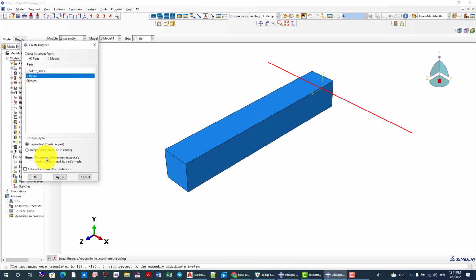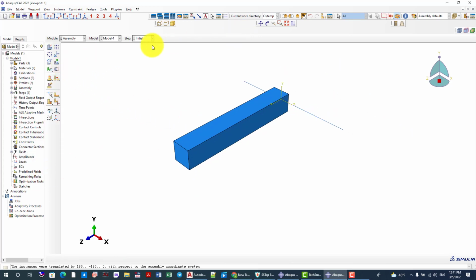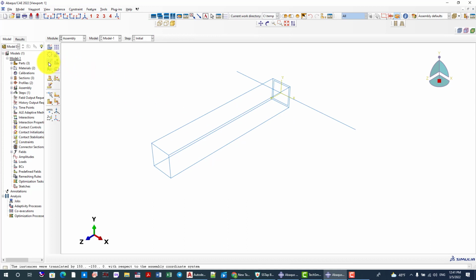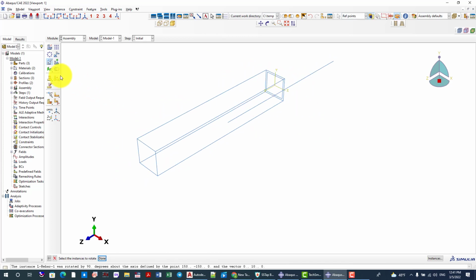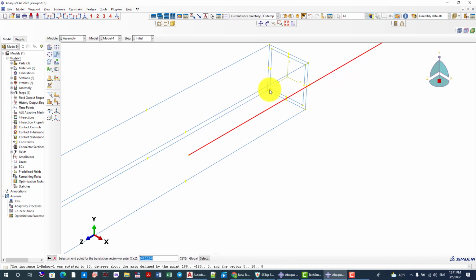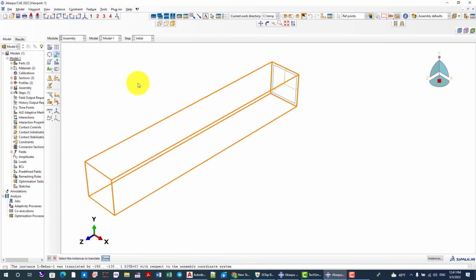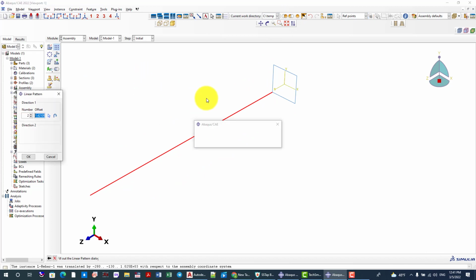And the last one is this one, the longitudinal rebar. I'm going to rotate this one using this angle, and I want to take it from this point to this point. And the next, I want to populate that. So first select this one, I want to remove, and select this one, populate to the other two corners, 260, and this is also 260.